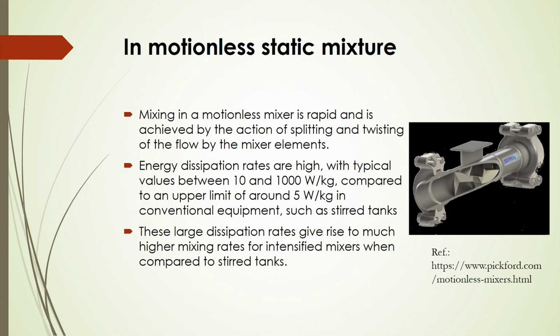And you see that there will be some energy dissipation rate, and it should be very high, because you are applying this energy to split and twist the flow by the mixer elements. And by splitting and twisting of the flow, you can have the formation of interfacial area between the phases. In this case, you will see that energy will be very high.